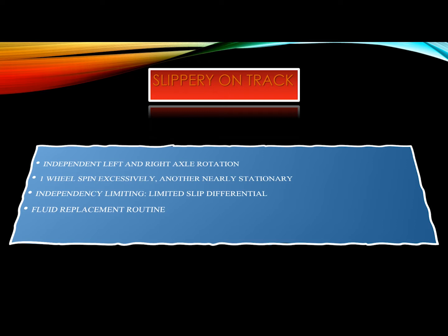This means high power supply to the slippery wheel and low power flow to the good traction wheel, so the vehicle cannot be moved. To keep the differential in good condition, we need to have its fluid changed regularly. This is because normal wear can cause the fluid to break down, which could cause scraping and friction.